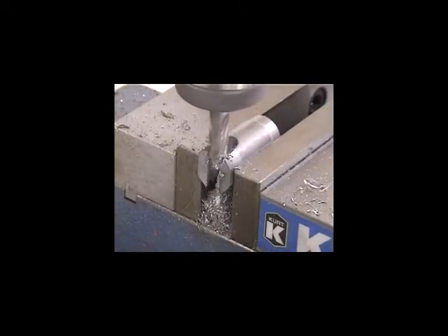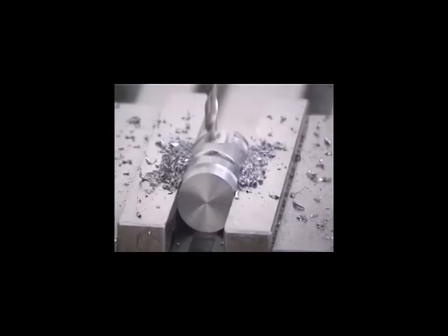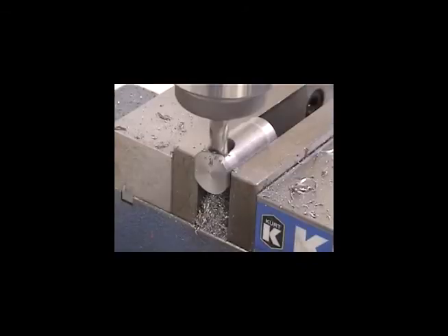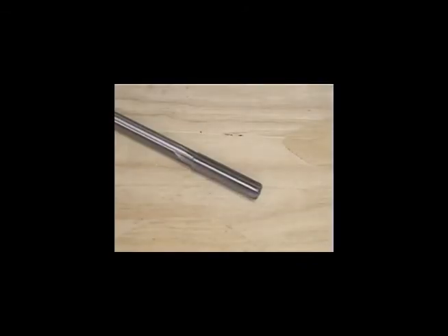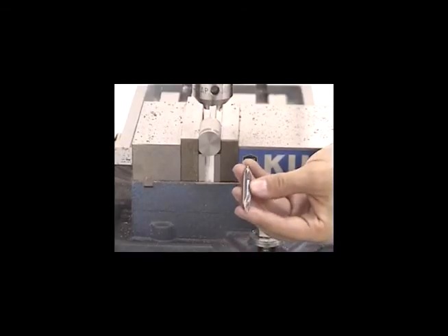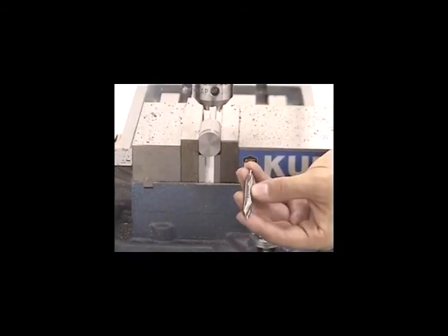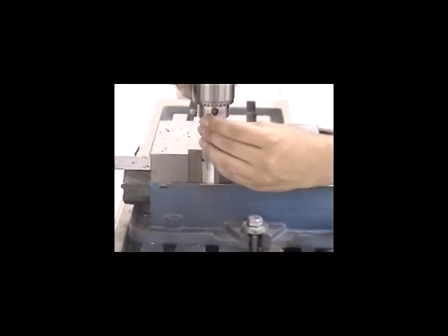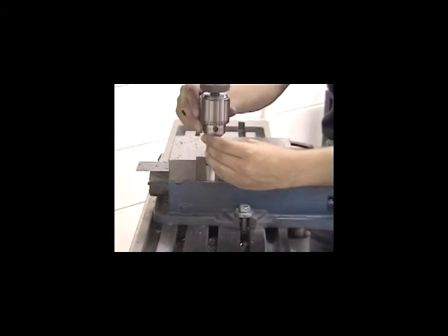There are several types of holes or slots that can be drilled and milled into a part. A drilled hole, a threaded hole, a milled slot, and a reamed hole. Any of these can also be countersunk. Most hole types begin the same way. The starter bit is placed in the drill chuck. The starter bit is relatively thick with a small drill end sticking out.